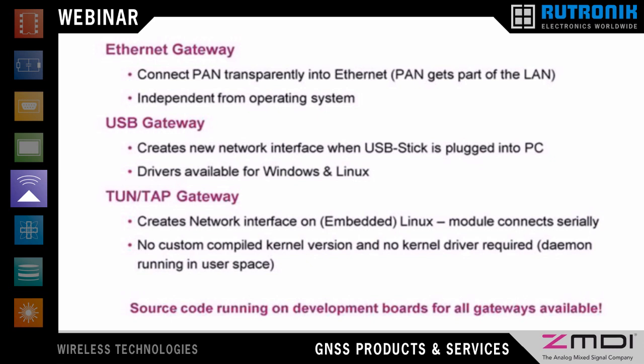So we have a sniffer to observe the network traffic, and the sniffer comes with a graphical front end for Windows and Linux. We have an over-the-air update front end where you easily can broadcast a new firmware to the existing modules in your networks. And we recommend Rowley's Cross Studio for the development, and for this we have some support packages. So you just easily install the support packages, and afterwards you can create a new project for our modules.